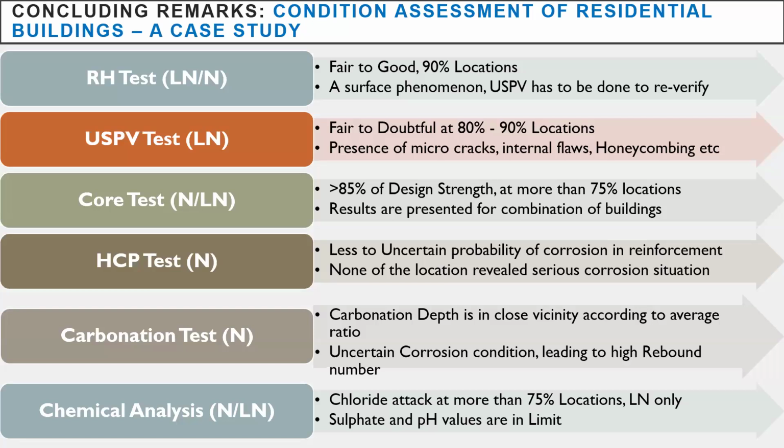Okay, carbonation test. Carbonation depth is in close vicinity according to the average ratio, but this is again an uncertain corrosion condition, because at about 85% of the locations, the carbonation front is yet to penetrate the reinforcement.